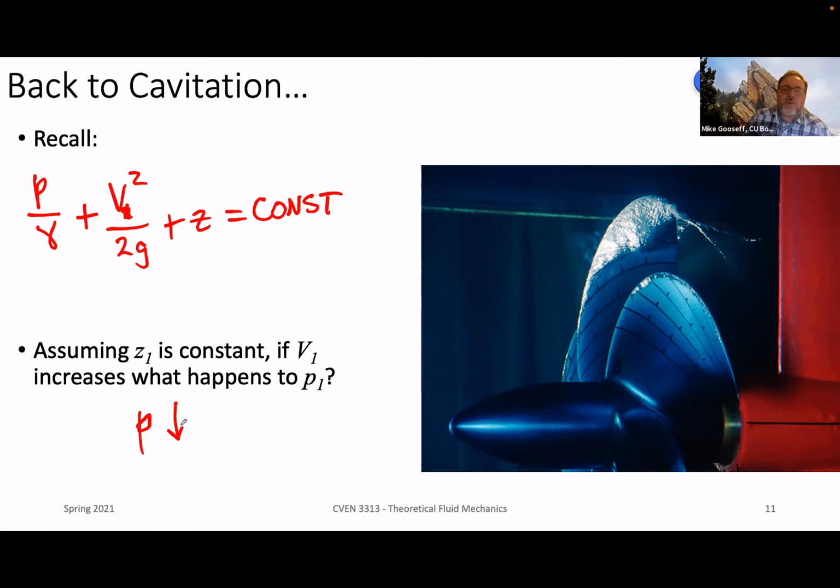So this could happen in a pipe, including this underwater motor on these fins on the right hand side. Note that it can also happen in just an open water system. What you can see here are all bubbles that are forming because of cavitation occurring. The blade is spinning so fast that the water right around it is dropped to a pressure that goes below the vapor pressure, and that's when we have this cavitation occurring.